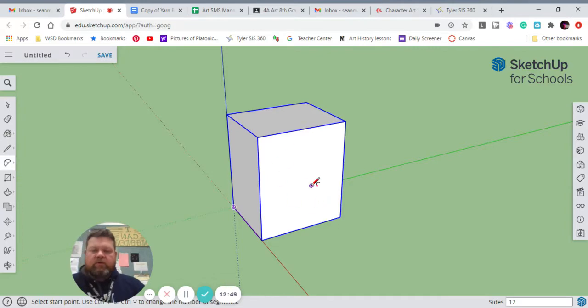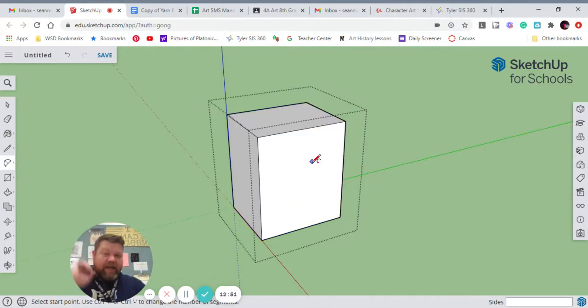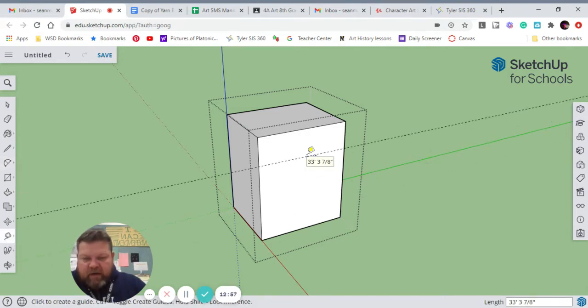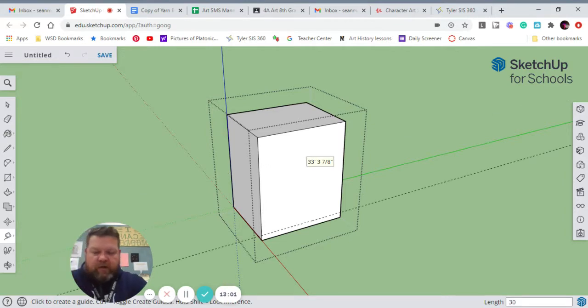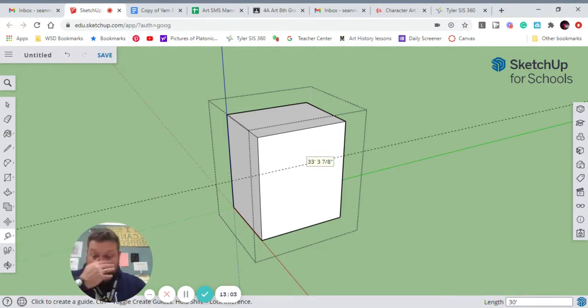So I'm going to do the 2-point arc. I'm going to open up my group. Check this out. Edit group. I'm going to go right here. Actually, I'm going to do this the right way. Let's put up, it's 30 feet off the ground. That's 30 inches. Sorry, 30 apostrophe feet. There we go. And then I'm going to drag a guide to the middle. So I know that's the midpoint because it turned blue. Now I've got myself some aiming points.